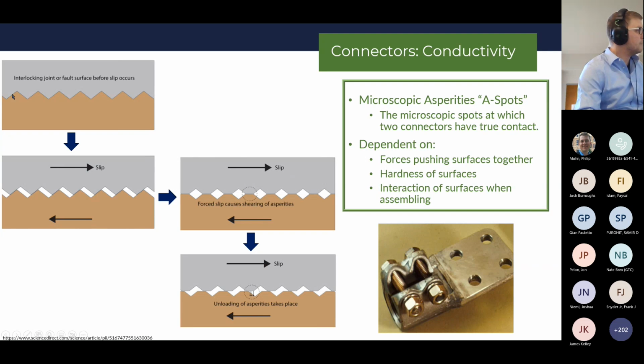Something else that will be inside of here, and we'll talk about it in a little bit, is the use of an oxide inhibitor. Now, when you press down on these, the forces are going to depend on the force of the two 4-hole pads pushing against each other, how hard their surfaces are, and the assembly process, making sure you're correctly tightening the bolts to the exact torque value that's required. And as I mentioned, adding that oxide inhibitor gives you the most sound electrical connection.